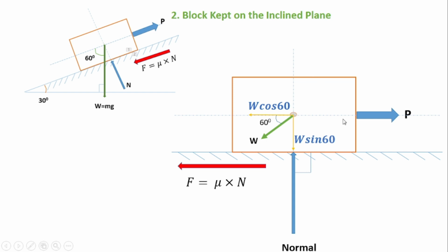If you draw this figure in this way, it will simplify it and there is a high chance that you will not make any mistake while solving this numerical, because it is very difficult to imagine, by observing the original figure, which is horizontal and which is vertical. One thing to remember is that weight force is the only inclined force. So if you show it like this and show the angles, it will simplify your FBD and you will be able to solve this question. Now the next thing is that we can apply the condition of equilibrium, that is summation of Fx = 0, summation of Fy = 0, and we can solve this numerical.